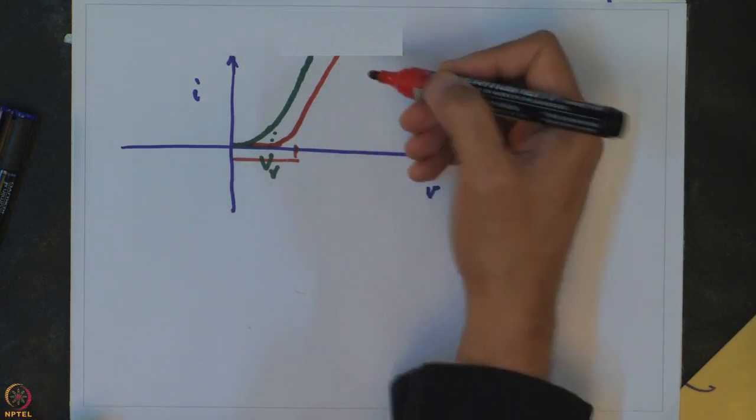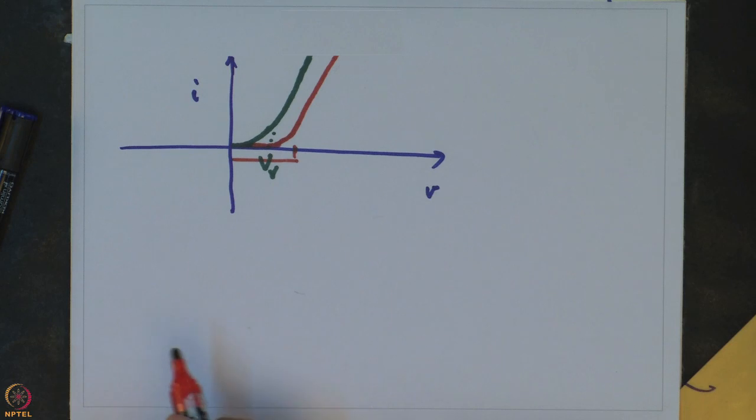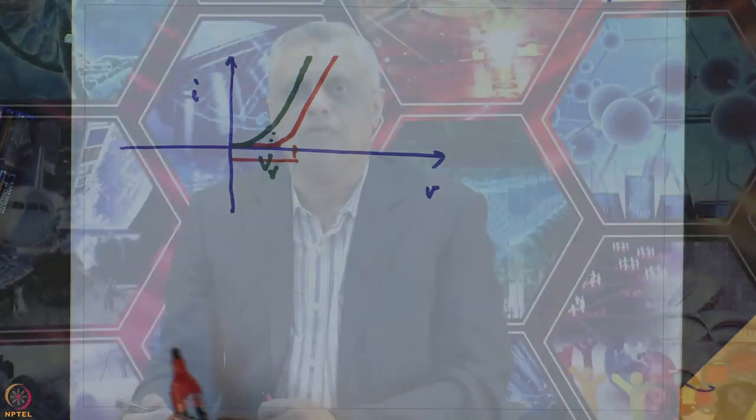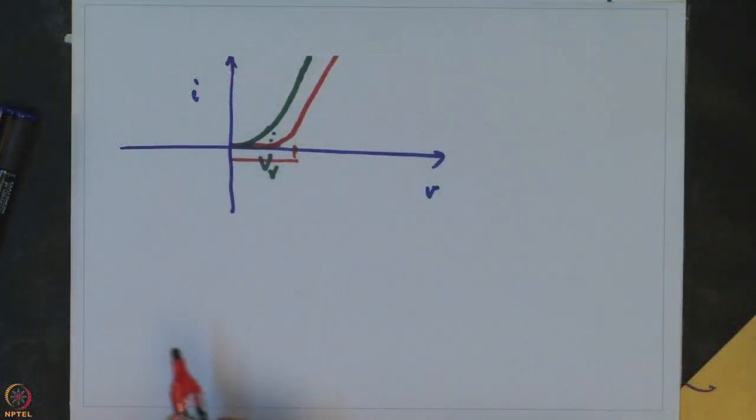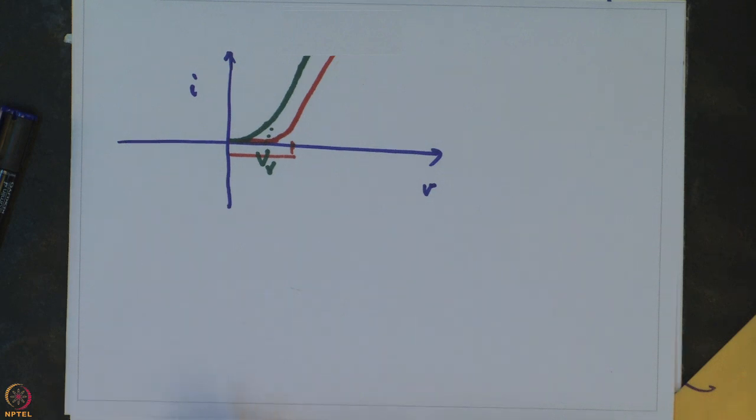This linearity is coming because you have an N minus layer in this device, which has much fewer charge carriers and therefore contributes to more ohmic voltage drops, which brings in this resistance type characteristic. So, that is why instead of an exponential in the green one, you see this linear plot in case of the power diode.